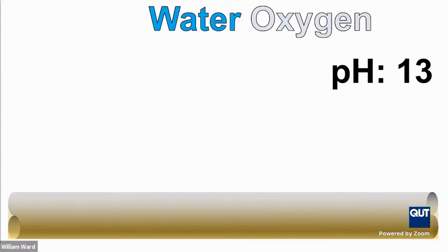So we're talking about rust, particularly rusting of steel. We need a certain chemical environment to deal with that. So we need water and oxygen for the corrosion reactions to occur. But water and oxygen alone aren't going to be enough to promote corrosion because we have that protective layer on the steel. But first thing is, if we can stop that water, dry out the slab or other concrete element, or we can somehow stop the oxygen, it's going to either change or halt the corrosion reaction.